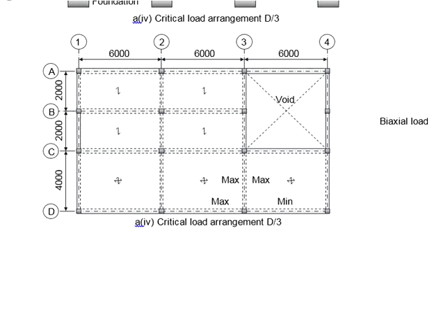In summary, columns A3 and B3 will have uniaxial bending to the major axis. Columns C3 and D3 will have biaxial bending on both axes. So later, when you need to design the reinforcements for those columns, especially on the dimension side, you will need to be extra careful whether the bending is towards the major axis